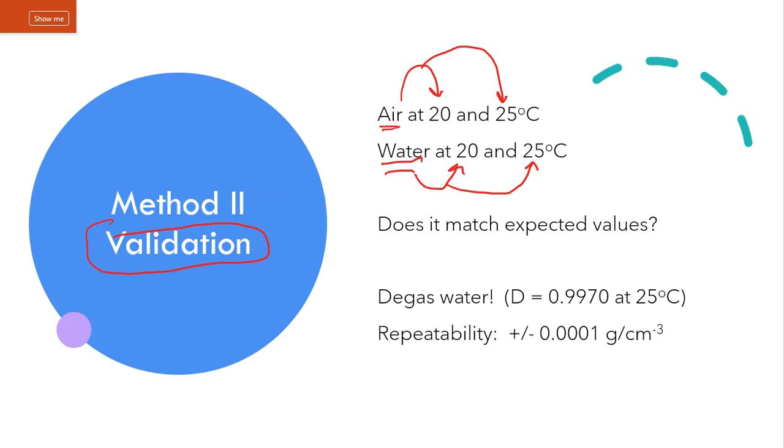So we go through this motion every time we use the density meter or on a scheduled routine basis, and we create a log, and we make sure that this instrument is in line with what we should be seeing, and if it ever goes out of whack, then someone's got to come in and someone's got to fix that a little bit better for us.